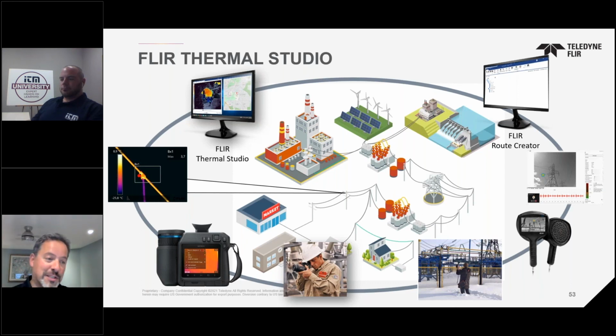With a thermal imager, you have to wait for it to run, and then check whether it has heated up. So even though thermal is the best for other applications, in the case of acoustic, it really picks up things early on. So yes, it can be used to look for problems with bearings. When a motor is unbalanced, bearings are going to be impacted, guaranteed. You won't see the vibration of the motor, you'll see the bearings not rubbing properly. They're starting to create acoustic ultrasound. You can probably pick it up with the SR124.